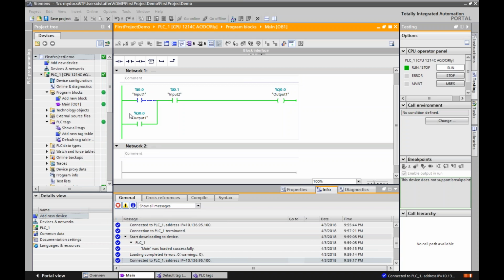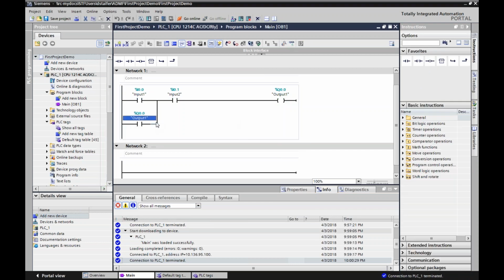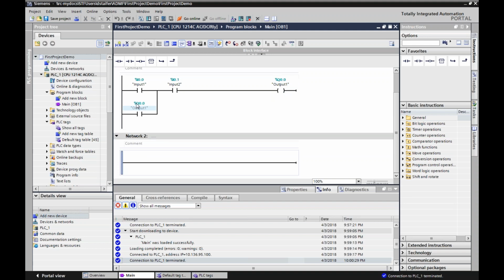But again, if we've done motor controls, we know there's things called interlocks. If I have one motor controlling reverse and forward and this, that, and the other, I need to make sure that there's things in place to keep the reverse from reversing when the forward is forwarding, or you get kablamo. Well, that's fairly simple. So if I go down to network 2, I'll just copy and paste this logic because I'm kind of lazy and I want to.